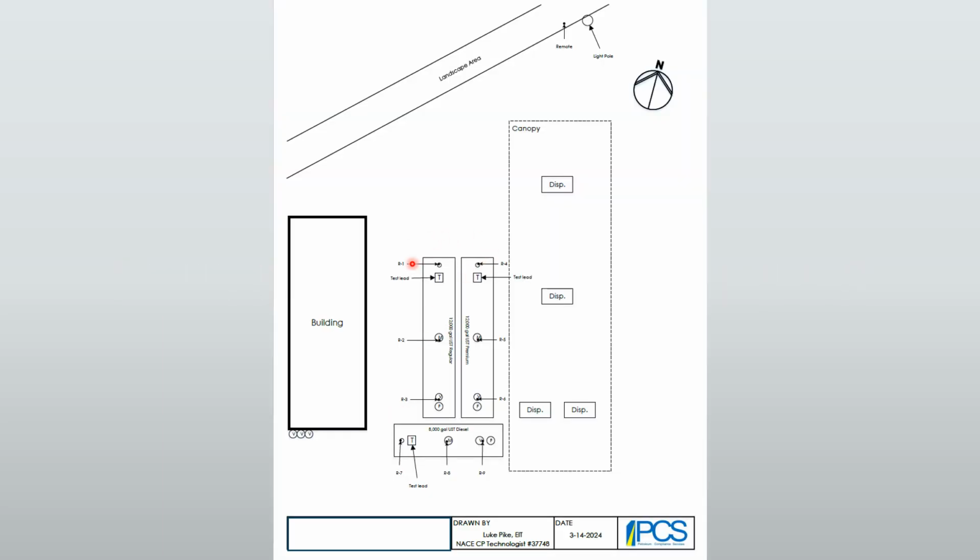So I try and get a reading on every third of the tank if possible. Again, sometimes the soil access is not available. I want to measure or mark where I'm testing next to. So monitors, turbines, fills, vents. Want to indicate where your remote is, landscape area.